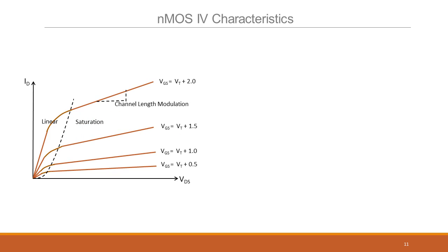Okay. Unlike the bipolar transistor where the saturation happened when both the PN junctions were forward biased, right? This was called the forward active and this was called saturation there, right? Here it is called linear and saturation. This is now not from device physics. These terms are from designers now. You can see the current is kind of linear here with VGS, right? And with respect to VDS both. And hence it's called the linear region. Here the current is saturated except the channel length modulation. If we neglect that effect, the current is actually saturated, hence it's called the saturation region. Okay.